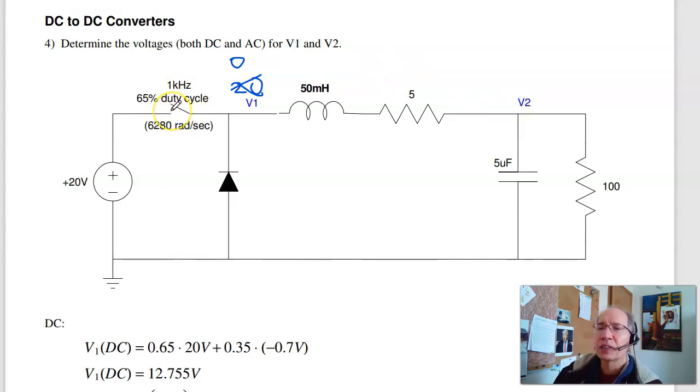That's what this guy does. The purpose of the inductor is to serve as a low-pass filter. At DC, this has no effect. At AC, I have voltage division. Say this is 300 ohms AC. This reduces the ripple by a factor of 3. This reduces the ripple even more. If this is 20 ohms, that's 1/5 of 100. That reduces the ripple by 80%.